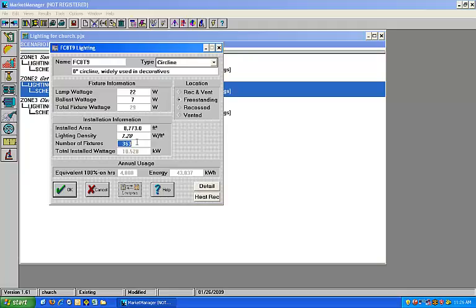We'll use that, and you can use that as your rule of thumb, and then maybe when you're calibrating, change it to maybe 1.1 or 1.4. Or what I often do is get a lighting audit report from someone else who's counted all the lights and knows the watts per square foot, and I'll look at some representative areas, average those out, and then use those averages.